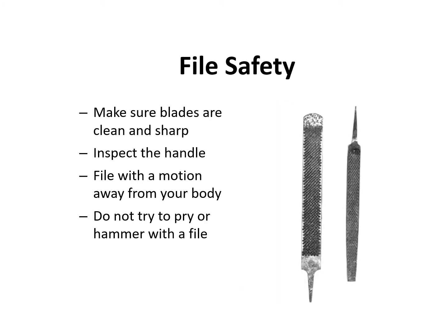When using a file, make sure the file blades are clean and sharp. If the file has a handle, inspect it for any signs of damage such as cracks or splinters. File with a motion away from your body. Do not try to pry or hammer with a file.